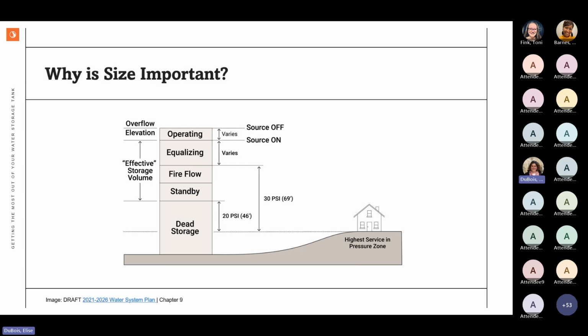After that, we look at your tank height. If you're over 100 feet, we're going to skip past those sheet flow mixers because we know they're not going to work. If you're around 80 to 90 feet of tank height, we're going to definitely consider them, but we're also going to look at the bubble mixers. We use the bubble mixers when you have tall tanks. When all else fails, we like a good bubble mixer because they're almost always working.